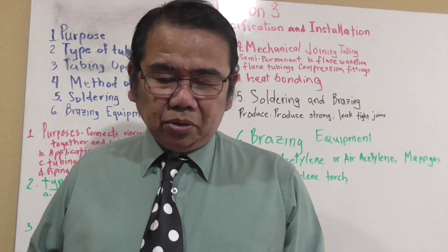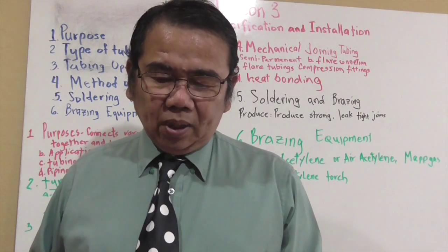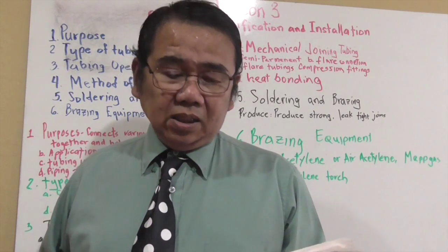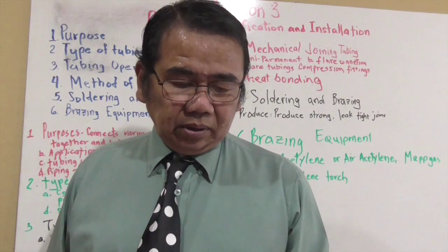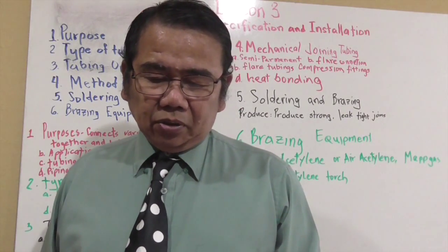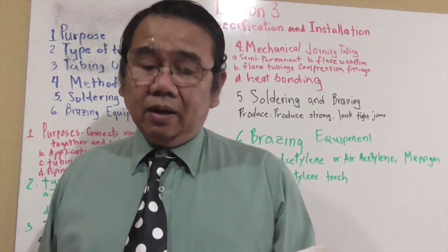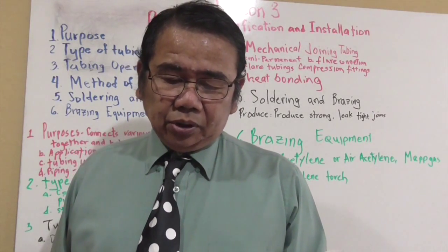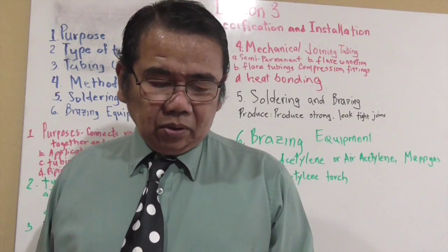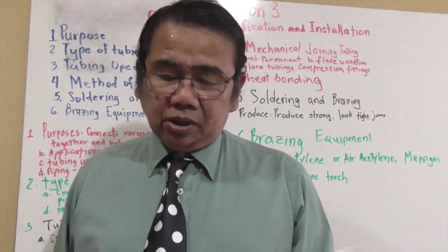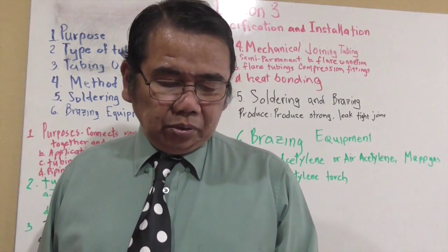The amount of silver in the solder is affected by what type of metal is being soldered. High temperature silver solder can be applied with oxy-acetylene or air-propane torches on small tubing. Oxygen acetylene torch is the most common use.